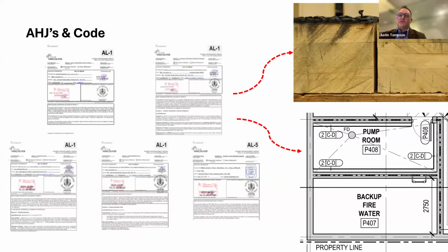So in a seismic event, if the water connection from the city is sheared, this is a 2-story water cistern in the parkade and a fire pump on the emergency generator that would be able to sprinkler the building in case of an event.